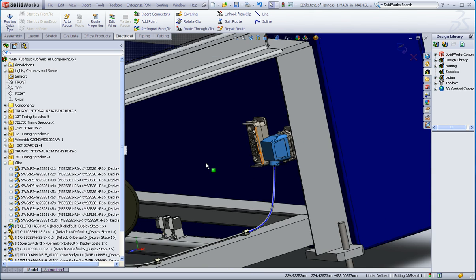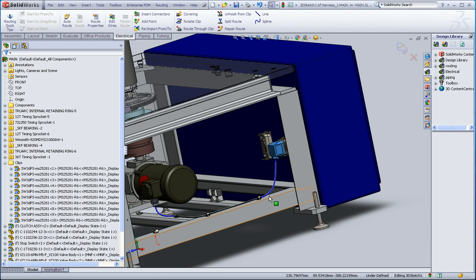The next stage in the process would be to take us from our harness to either a flattened form board harness, or to an actual documentation style, or to an actual form board style. So here the choice is how we present that information and who takes ownership. So we could actually do the harness inside SolidWorks, or we could take the harness back into E3 Wireworks. It's entirely down to the individual company and users as to what their preference is. The lengths here can be transferred back into Wireworks.